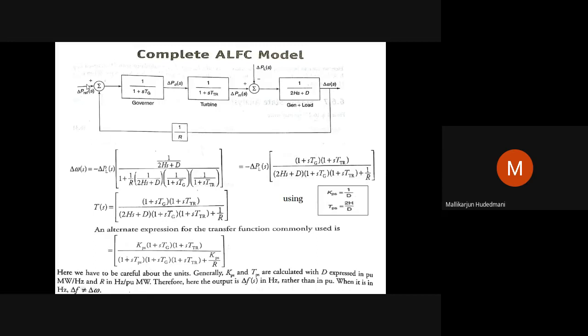It means the original set point which made everything perfect, due to change in loads, this error is noticed. This error is noticed from this generating plant and load area, that is causing either delta PL to occur or D to change its impact. Because of this block's reflection, delta omega is resulted.